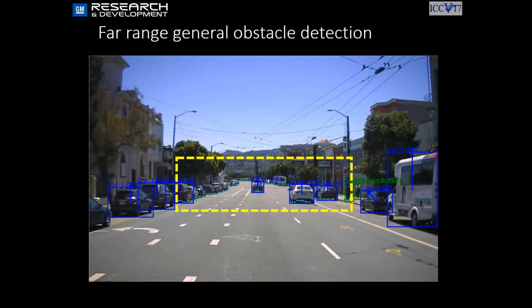Another such example is the ability to do obstacle detection at far range. If you look at the small white triangles, you can see that what we have here is a StixelNet, which operates on ranges up to 120 meters. And it was trained using a LiDAR that can detect obstacles only at a distance of about 40 meters. So how do we do it?